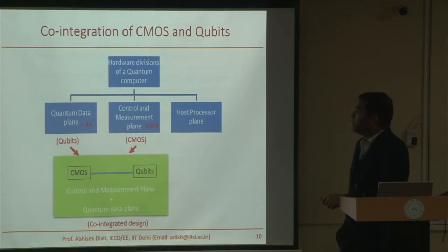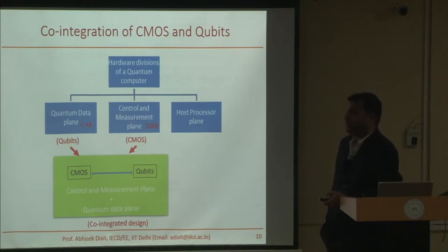Currently what people are doing, I'll also try to show you, but if you have gone through the papers, people are looking at a lot of heterostructures to make the qubits. They have a lot of accumulation and depletion gates to concentrate the charge in one place, right? And then using a designated single electron transistor which is monolithically integrated, you detect as the charge goes from one quantum well to another, right?